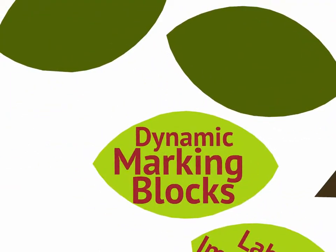Dynamic marking blocks. I can now predefine a set of marking block information that I want to be included on a plate part, for instance, along with some parameters that I may want to have filled out at the time that it gets inserted. It exists as a standard in the library where, as I'm structurally modeling, I can drop dynamic marking blocks wherever I need them. Alignment marks, for example, is a good example of how I can use these, right?